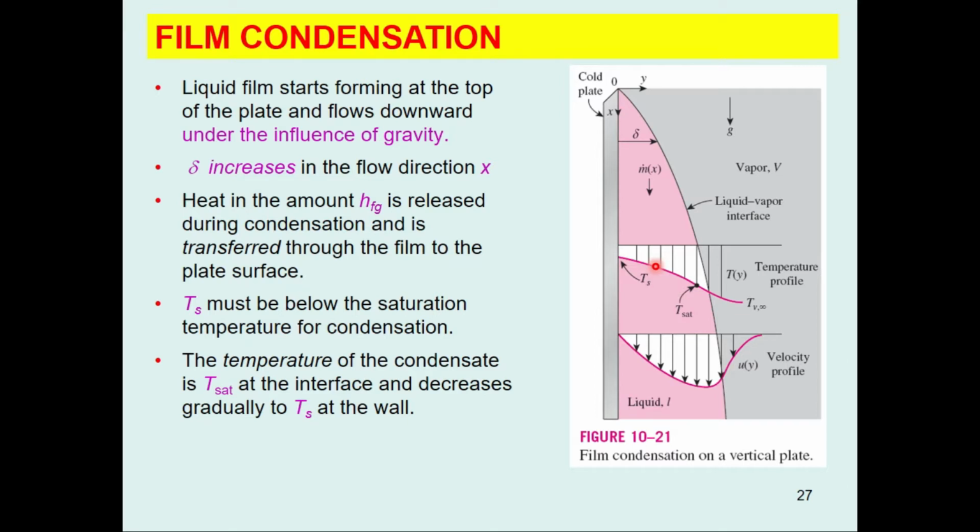So usually we consider that the condensation is occurring at this point, slightly below the saturation temperature, and the amount of heat released at this point is known as the latent heat of vaporization. Sometimes in real processes, the actual condensation takes place at this temperature. If it does, it will release more heat in the actual process, so the actual heat transfer will be larger.